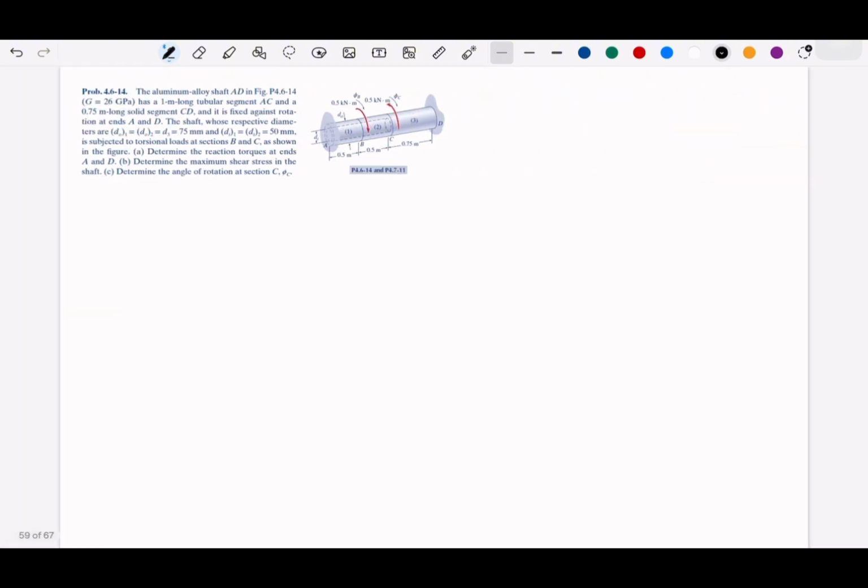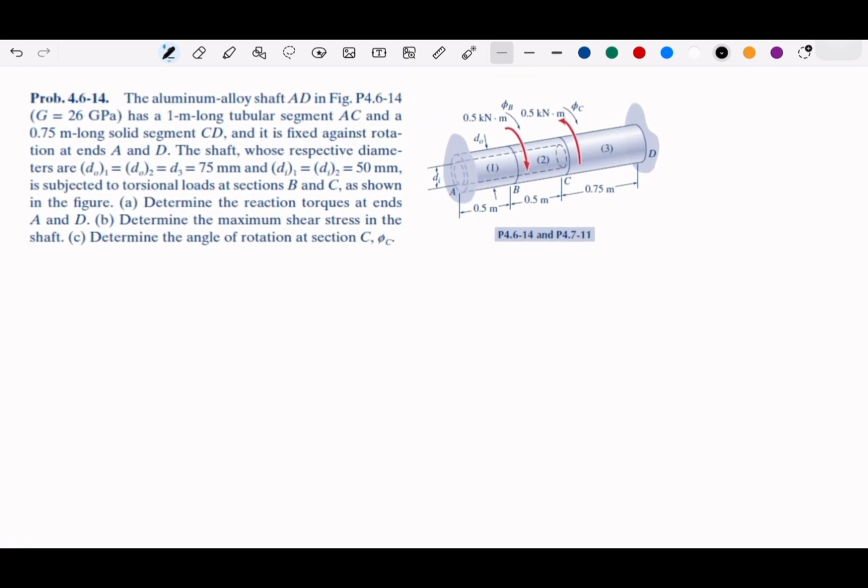Okay, let me continue. So this is another question, and I think it's quite similar. The difference is we have two external forces at B and C, which give you different equilibrium, but the procedure, the steps, will be the same. So first, going for free body diagram, equilibrium, and then we can go for either inertia or finding the twist angle computations. And we can have the geometry of deformation, use compatibility equations.